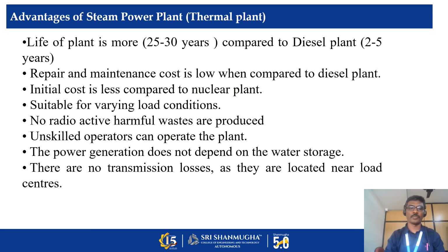Advantages of steam power plant. The life of the plant is 25 to 30 years, more than a diesel plant. Repair and maintenance cost is low compared to diesel. Initial cost is less compared to a nuclear power plant. Suitable for varying load conditions. No radioactive hazard. Unskilled operators can operate the plant. The power generated does not depend on water storage. There are no transmission losses as they are located near load centers.